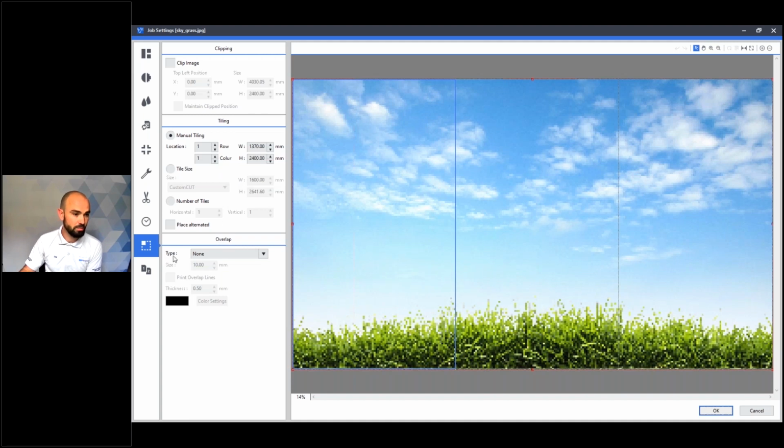So first of all, down the bottom here, it says overlap. Now, as I mentioned earlier, normally you would have a slight join to your tiles so that they actually go on top of each other. By default, there's no overlap applied, but we can add an overlap either in the top left corners, top left sides, or all corners. Top left means that wherever there is an overlap, either on the left-hand side, so where they join in the middle, or the top edge.